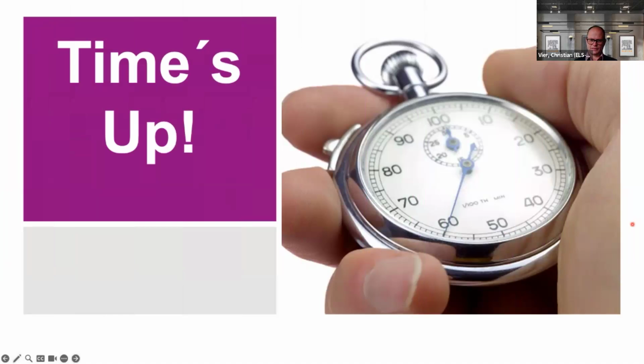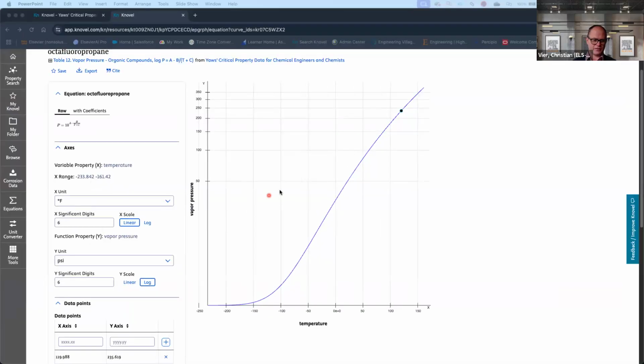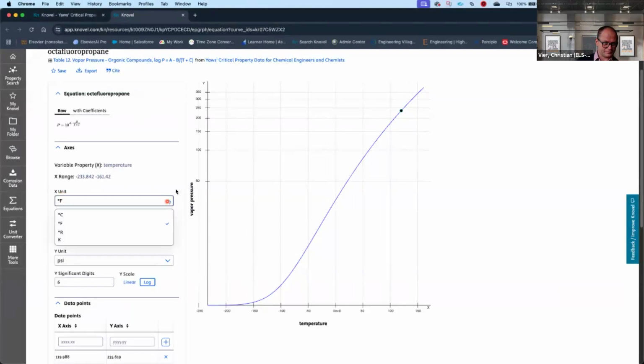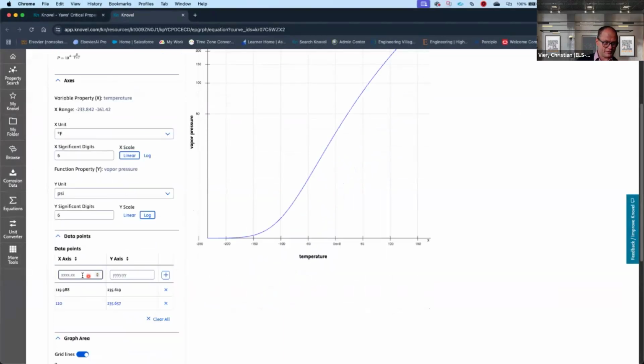Nice. Thank you very much for participating. The time is up. And I see many good results here. But I want to talk you through it again. Okay, so you took the link from the chat. You went into the X unit, you changed it to degree Fahrenheit instead of degree Celsius. The Y unit to PSI. And then you go down here to the X-axis and you entered the value for 130.